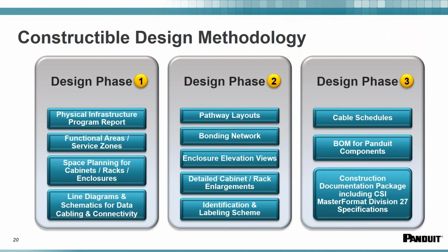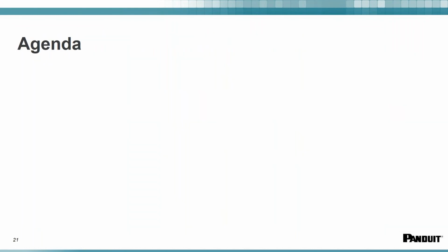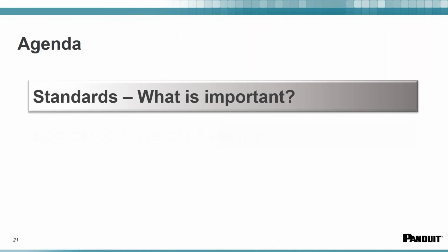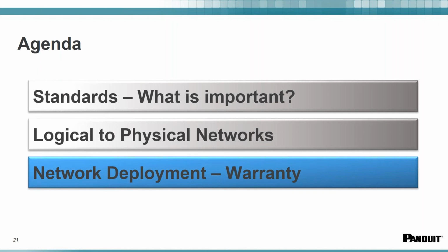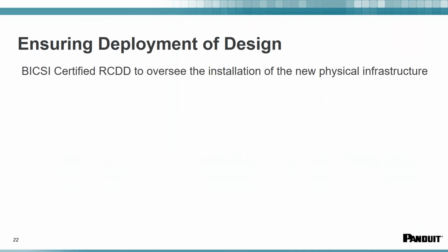And deploying it will take you to another layer, as RCDDs have to now take the physical design and use what we call certified technicians that know how to run the fiber, how to terminate it, how to make sure that you've got acceptable losses in the architecture, to ensure that the installation is done with the design specification in mind.